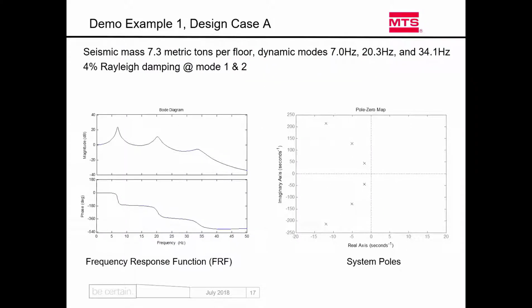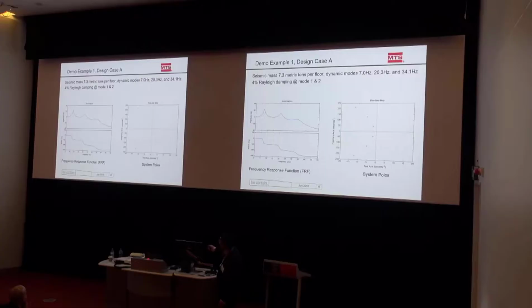So what happened is that, for example, that's the frequency response function or the transfer function of your hybrid system. This is the reference system before you divide the system. It's like the whole structure. The 3 modes, right? These modes are quite high. 7 Hertz, the third mode is like 34 Hertz. Quite stiff structure. Because of the braces, the steel braces make it very stiff.